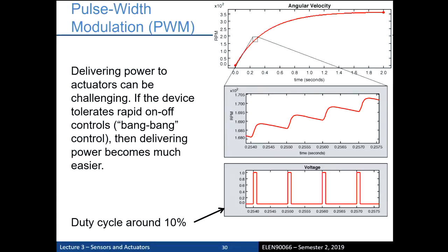Okay, so we use PWM to drive the motors. Indeed, that's how the motors on the Kabuki robot are driven, by PWM, because it's much more efficient and it requires simpler circuitry. It's easier to build a switch that switches large currents on and off than it is to build an amplifier that can handle large currents but also fine-tune them. It's very difficult to build amplifiers like that. It's easier just to build a bang-bang controller like that.